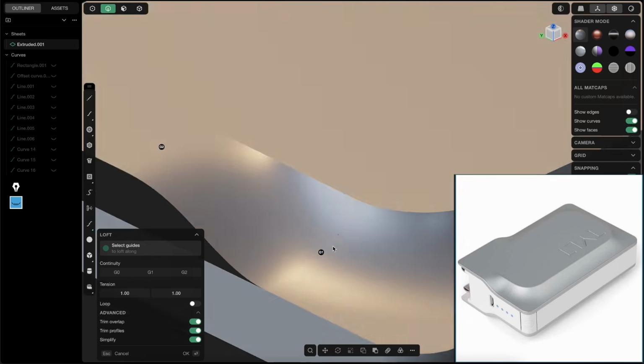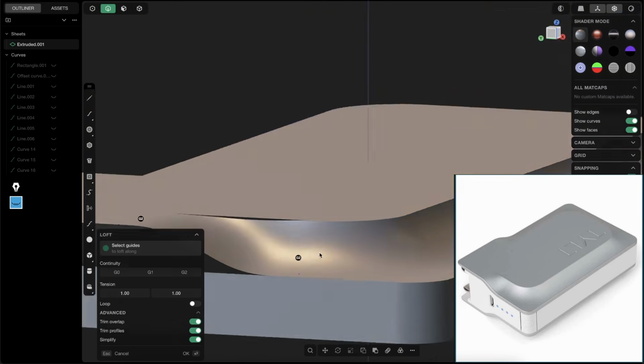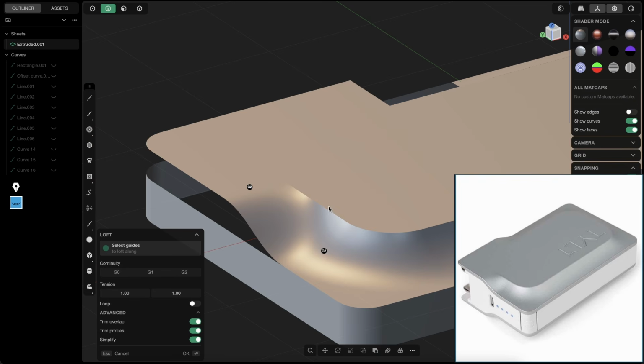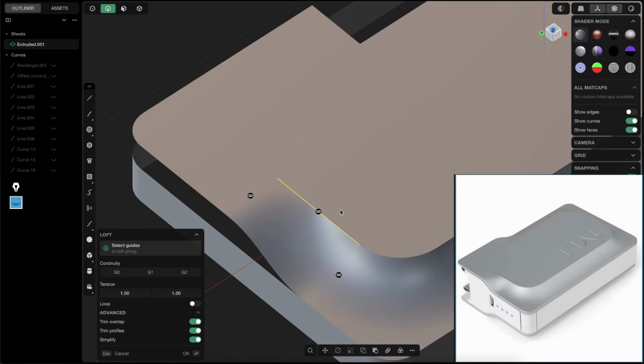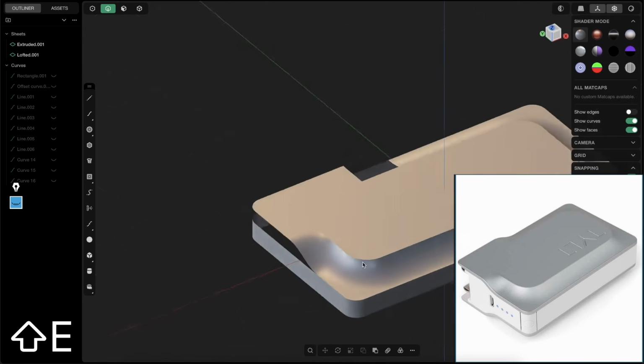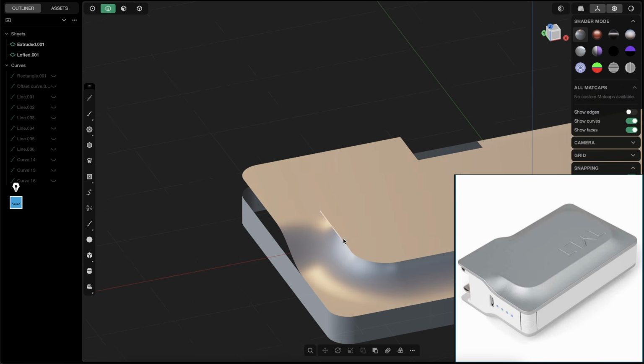And if you render that, you will not see anything. But here we can perfectly give G2 because we have some space. And you see everything just looks super smooth. And now just add this edge with shift click and give it here G0, obviously, right? So you see everything is nicely glued together, and it looks a little bit weird here, and we will fix this in a second.